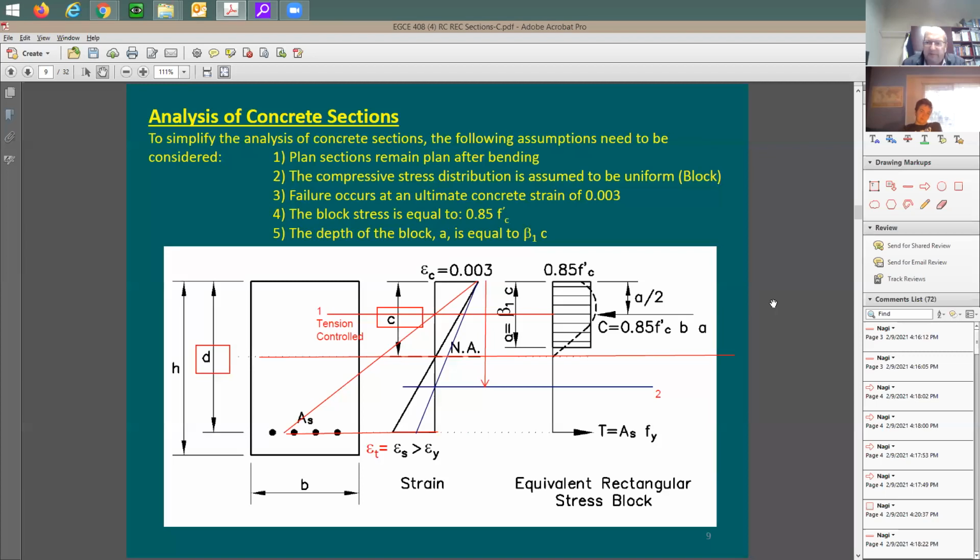This is going to be my assumption, right? In some cases, beams would have a little bit of external axial compression. But in this case, we assume that there is no axial compression force on the concrete beam, just moment. And the moment is going to be resolved into tension and compression components. Now, for equilibrium, again, C is going to be equal to T, meaning that As times Fy equals this ordinate of the stress, 0.85 f'c, times the depth a, times the width b, which means the volume of this compression block.